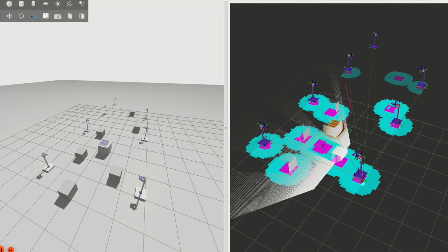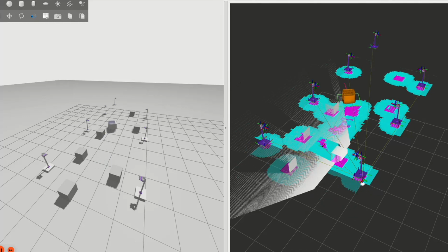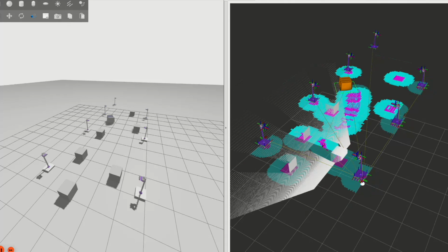We have a few plans to improve our current setup, and this involves dynamic mapping. It should be trivial to enhance the cost map with dynamic information from stereo camera depth images, generating point clouds for more accurate local control. The local cost map will roll with the robot using data from the nearby infrastructure nodes.